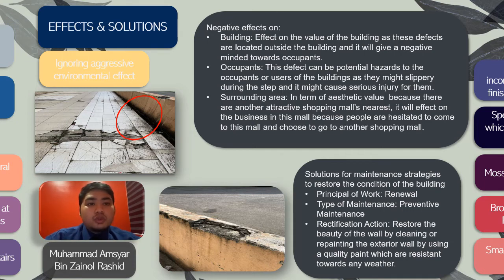So the solution for these defects is: principle of work, renewal; type of maintenance, preventive maintenance; and last, rectification action is to restore the beauty of the wall by cleaning or repainting the external wall using a quality paint which is resistant towards the weather.